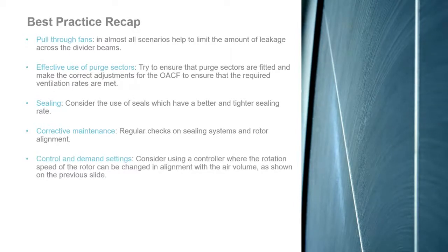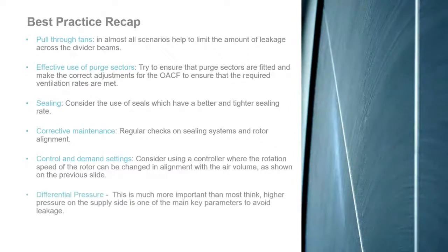Control and demand settings, as we saw in the last slide. Consider using a controller or a unit where you have that ability and function to modulate the rotation of the rotor depending on the various air volume settings. And then the differential pressure, which is not to be overlooked, and it has a much higher effect than you might think. So considering throttling on existing units, and also taking into account the pressure through the ductwork of existing buildings and new design buildings